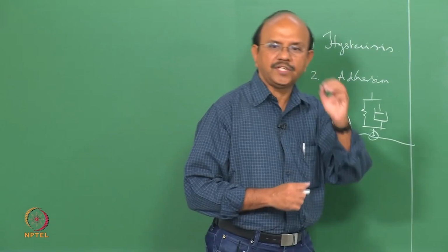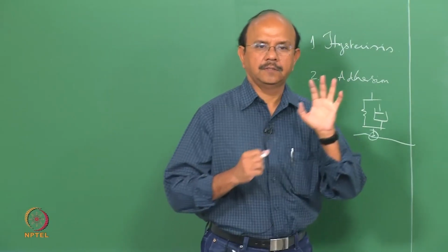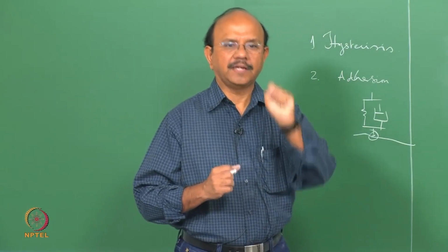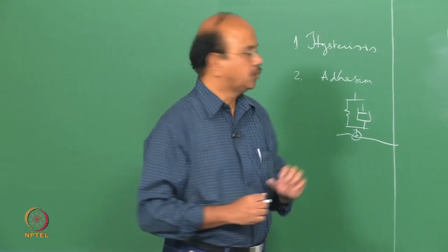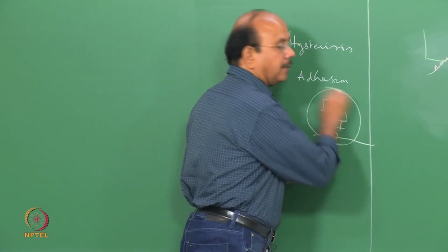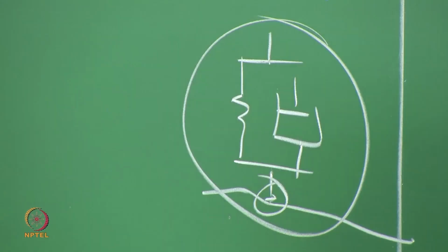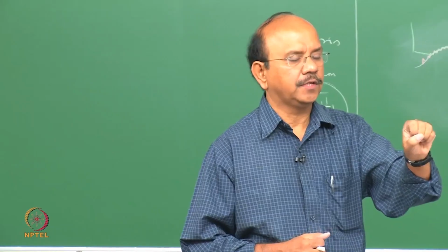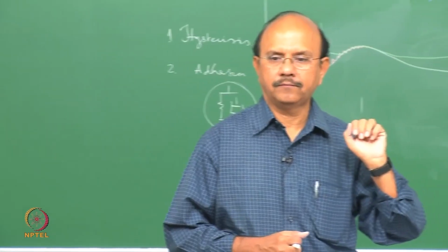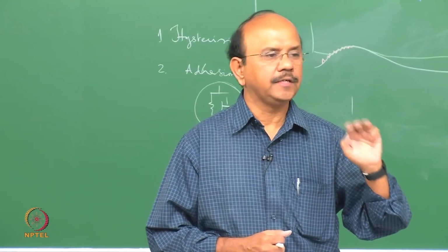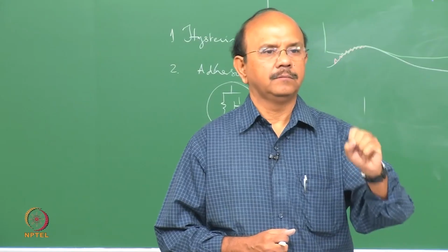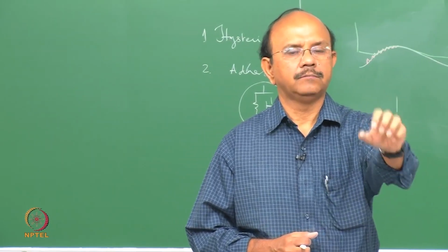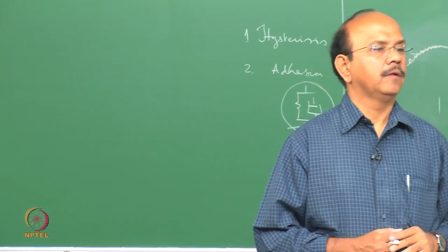So it sticks, breaks, slips, then again sticks, breaks, slips, and so on. So at the molecular adhesion level, there is a sticking, slipping, sticking, slipping, and so on. So it is the Van der Waals bond that forms, breaks, forms, breaks, and so on.